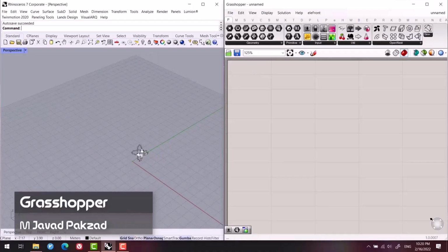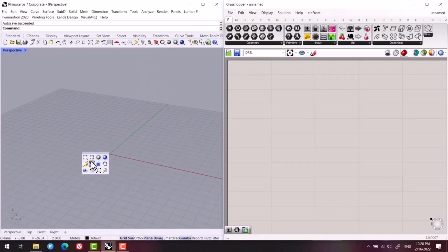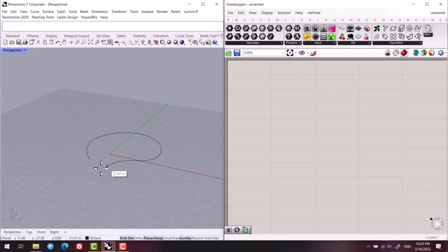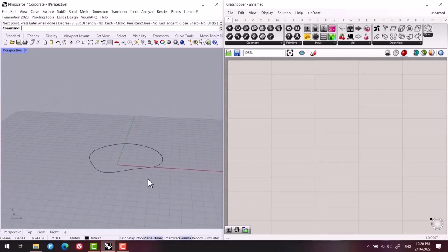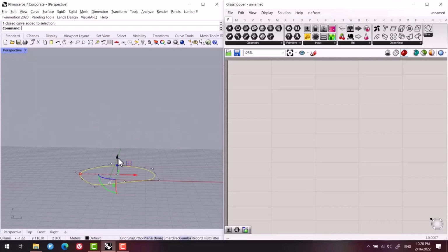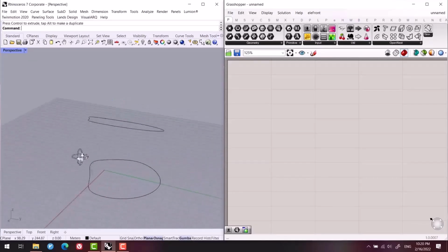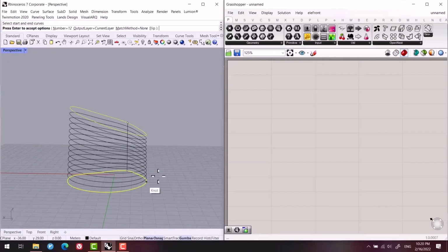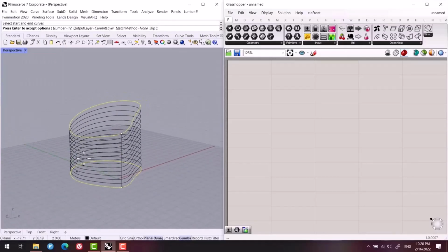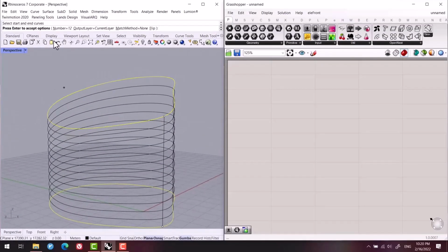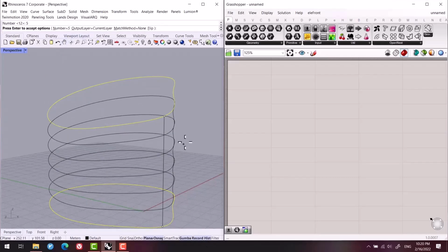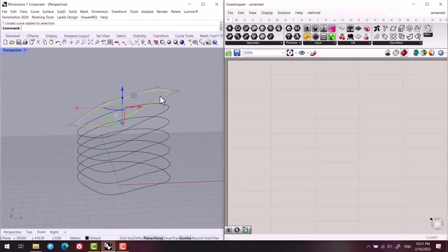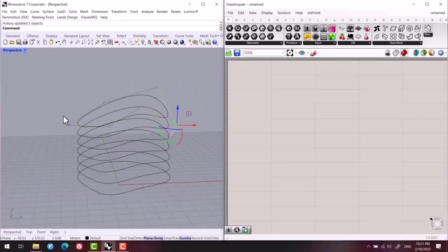In this episode, we're going to deal with the applications of the Twin Curve command within an example together. At the beginning, we have sketched a curve like this by using Interpolate Curve in Rhino, I make a copy of it, then I rotate it this way, as you can see. Then I start the Twin Curve command, and then I draw curves between the two specified curves, and in the command line I click on Number to specify the number of curves between the two original inputs. For example 5, like this.